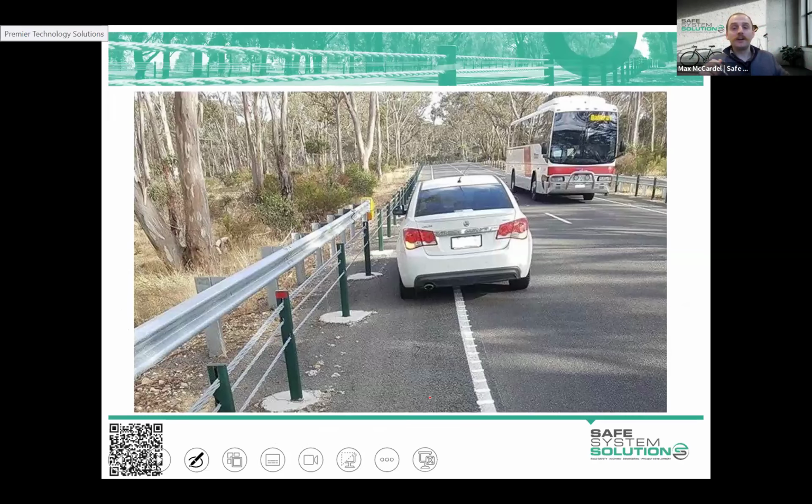One thing really worth mentioning though is if you are doing edge containment, think about what type of width you're able to achieve, because if you're not wide enough and you do have a vehicle that's broken down and they're unable to pull off the live carriageway, surely you can appreciate why that could be a risk.